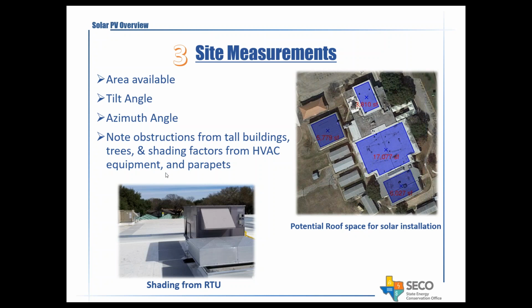And one other thing is that you have to stay away from the edges of the building, at least 10 feet, I would say minimum. Otherwise, you'll have to put railing and so forth if you're too close to the edge. So just something else to keep in mind while doing these projects.